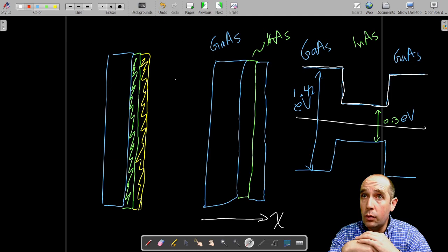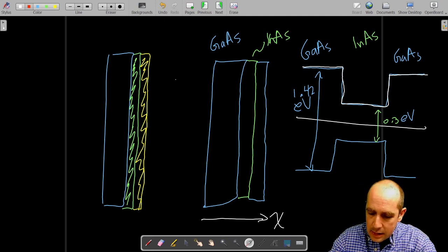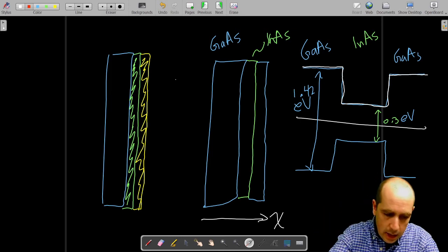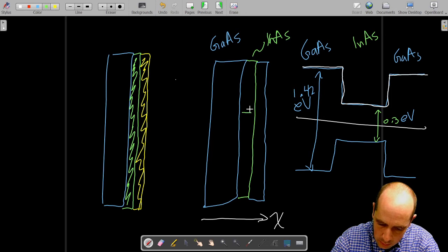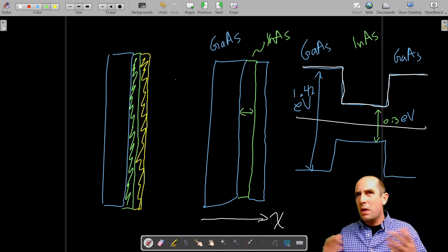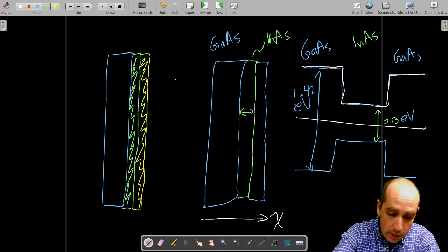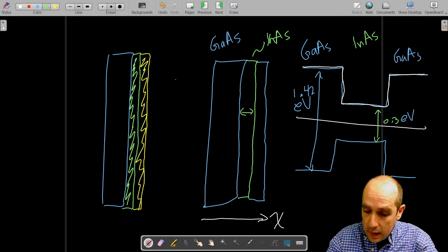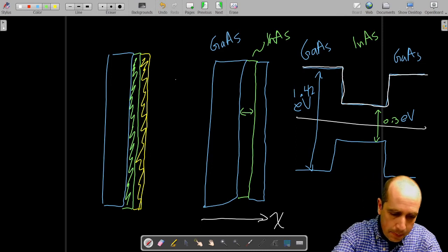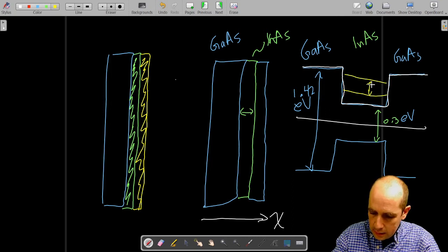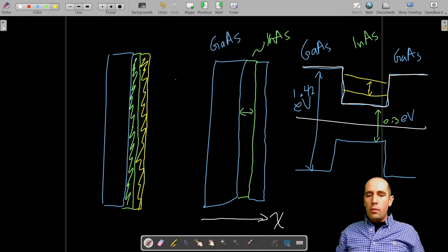They're actually something that we can make, and by making these kinds of wells, by deciding the width of this well, so how much material we grow here, if it's 1 micron or 1 nanometer or 100 nanometers or whatever, we can do, so to speak, quantum engineering. We can make a quantum system which will have energy levels spaced by a variable that we can control when growing the crystal.